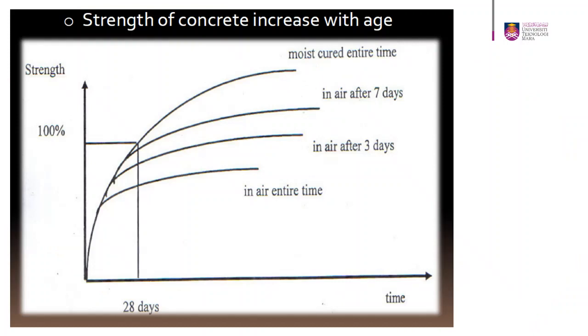Strength of concrete is defined as the maximum stress it can resist or the maximum load it can carry. The strength of concrete can be determined using flexural tensile tests, where the maximum load can be estimated with proper curing. Okay, so what is curing? Concrete curing is the process of maintaining adequate moisture in concrete with a proper temperature range in order to aid cement hydration at early ages.